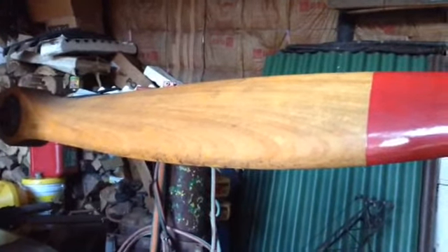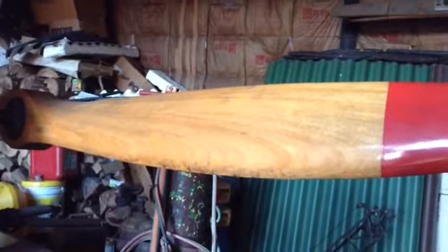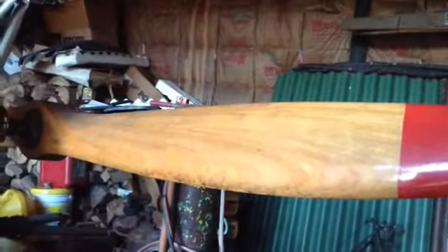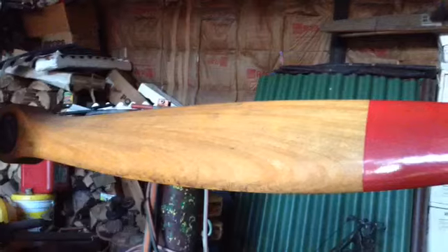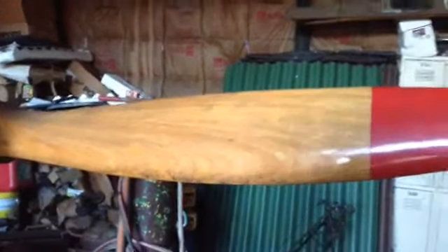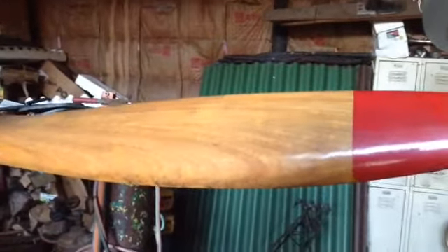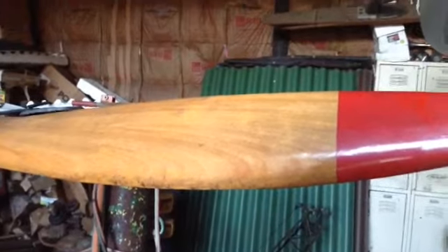Analyzing the propeller sliver by sliver from center to tip would give the most accurate estimation of the moment of inertia and consequently the radius of gyration. The website supercoolprops.com and some other websites say that the radius of gyration of a propeller is 55% of the way from the center to the tip. So the radius of gyration of this one would be 0.55 times 30, which would be 16.5 inches, and we're about out of time. We'll jump on this in the next section.